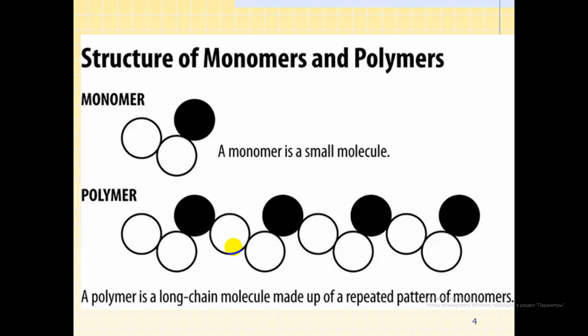Polyethylene is available in many different densities which determine its application. Polyethylene is classified into several different categories based mostly on its density and branching. The mechanical properties of polyethylene depend significantly on variables such as the extent and type of branching, the crystal structure, and the molecular weight.